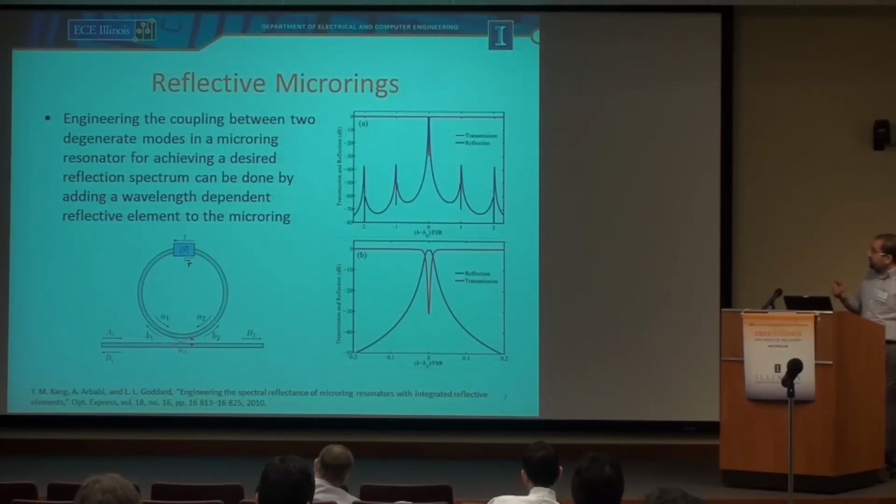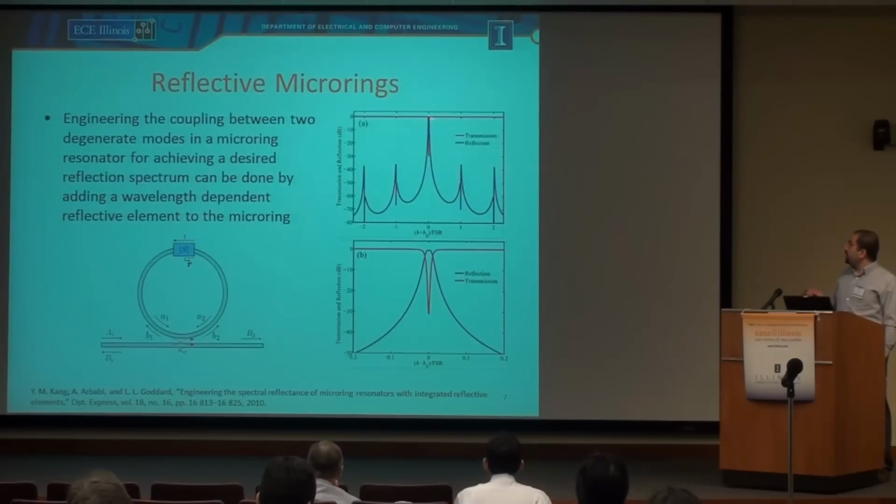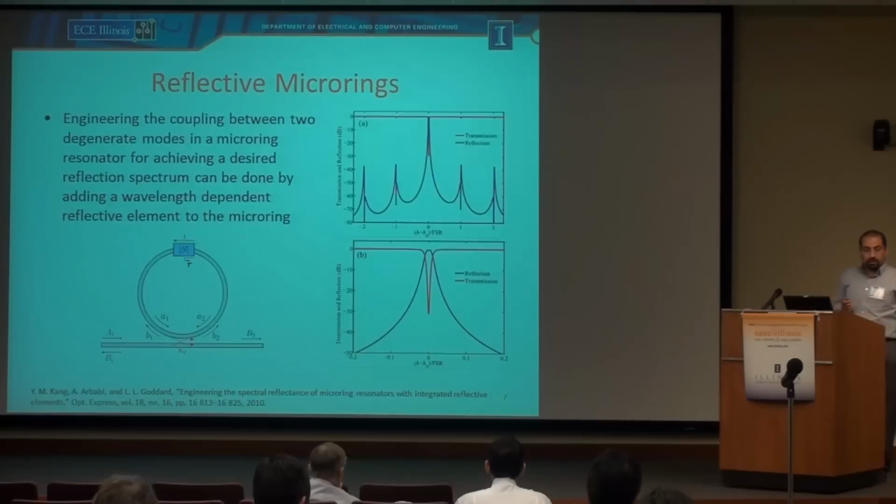For such a device with that selective spectrum, we can get a reflectivity of the total structure that looks something like that. We have a transmission, and there's a main reflection peak, the blue lines, and at that reflection peak we have zero transmission and a very large reflectivity. This is just a zoomed-in view of that one. You can see that it looks very similar to what I proposed in the motivation section, that we can have a reflectivity peak without any side modes.